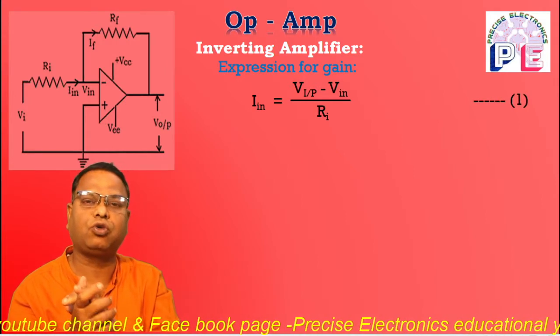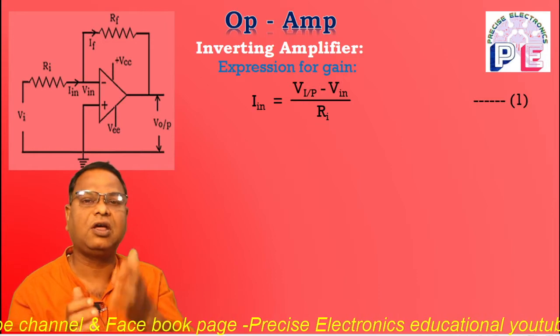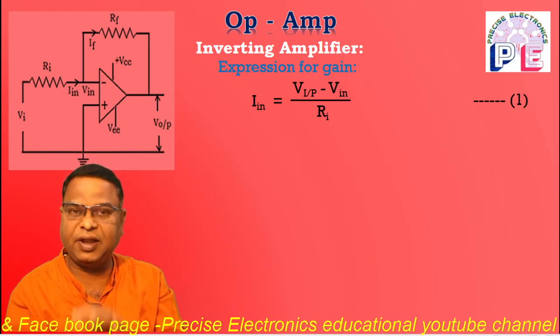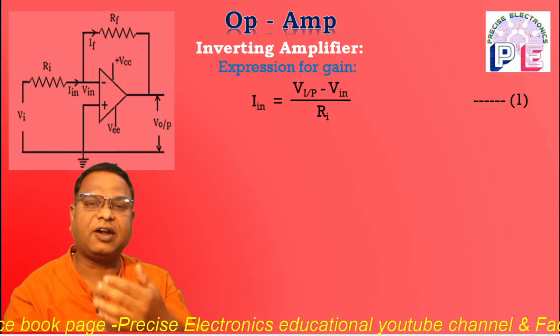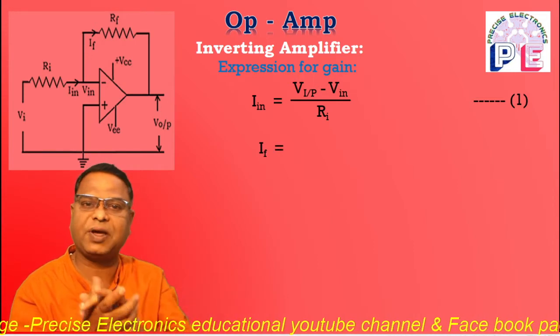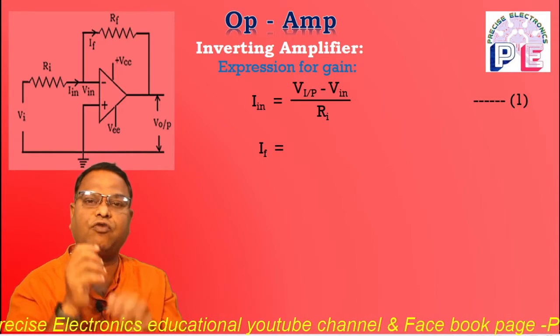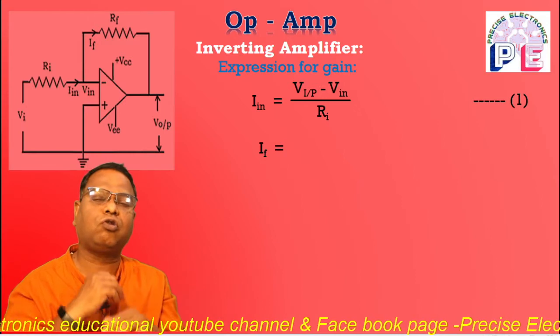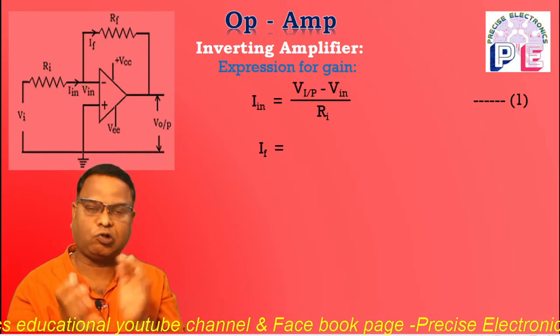I in is equal to V input minus V in upon Ri, equation number 1. Similarly, the feedback current IF: the output is fed back to the inverting terminal through the feedback resistor RF. So we have to find out the feedback current. Feedback current IF is also calculated by using Ohm's law.